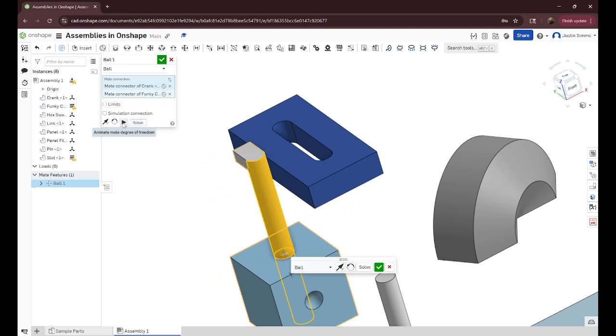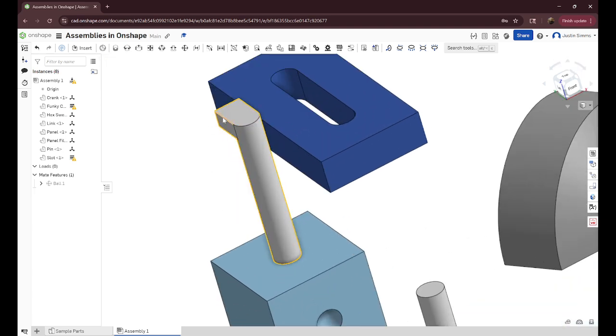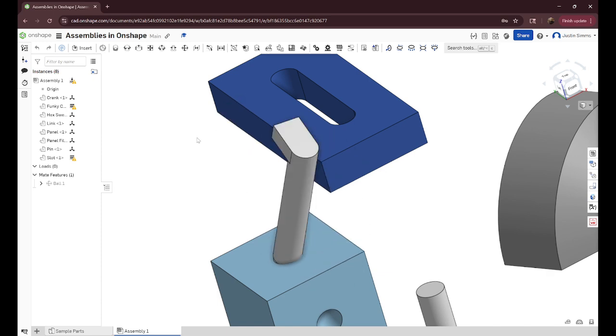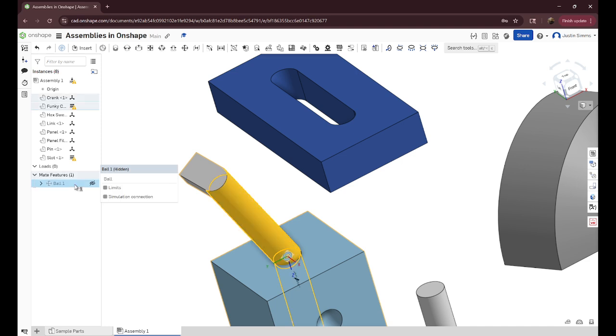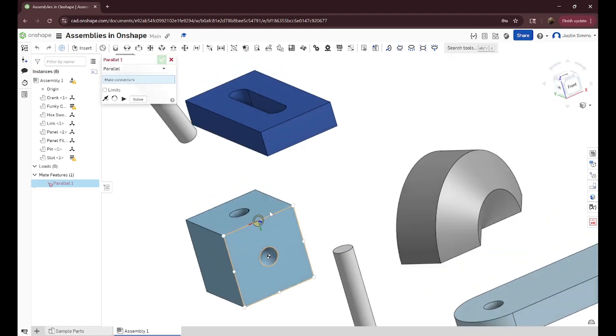And if I animate degrees of freedom, it can go all over and rotate, but it still keeps these two mate connectors in the same spot. This is really nice for certain features, especially if tolerance is off in your CAD somehow and you get it skewed. The ball joints can work really well for keeping two components right there if you can't actually keep them together.